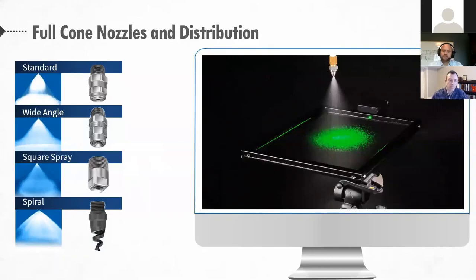Yeah, so spinning disc atomizers typically have, you can imagine a liquid feed at the center of a disc or a cone, and the fluid then flows down towards the edges of the cone or disc that's spinning, and a lot of times you'll have little teeth on the end. And so droplets will then be thrown off of each of those teeth, typically with larger drop size and also a pretty consistent drop size as well from a spinning disc atomizer.